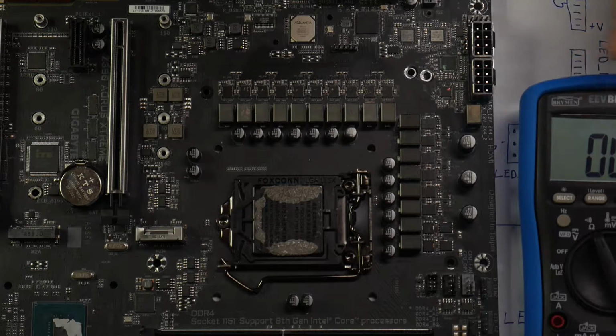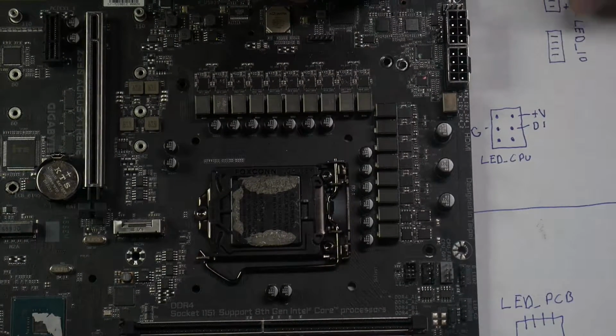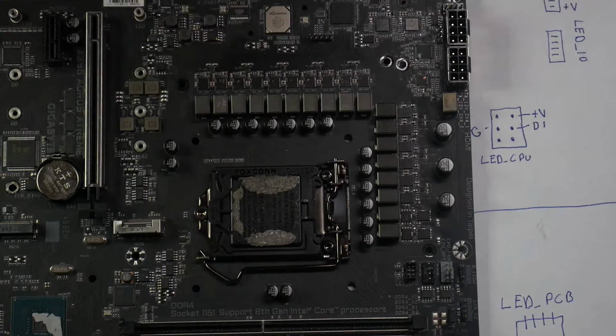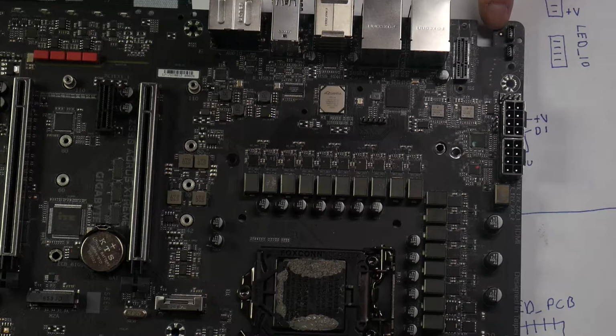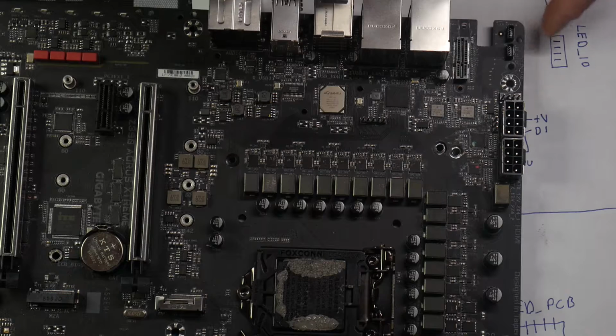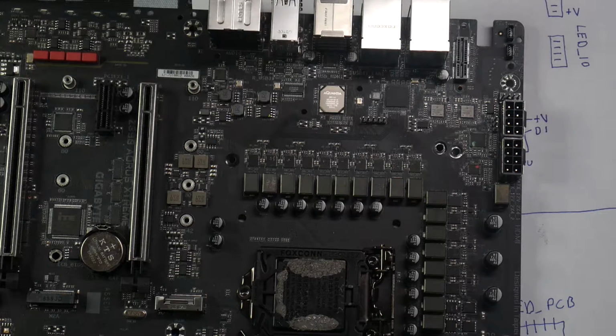So let me get back to my little mapping right here. So data in, and I don't know what this is until a little bit later. We'd have to test it out physically on the header, but the board's dead. And on this board, the Extreme Water Force edition doesn't have anything that plugs into this. It only plugs into the LED I/O, which we're going to test next. So we have 2 question marks for these two. One could be just not connected, or it could be connected somewhere else in the board, who knows.